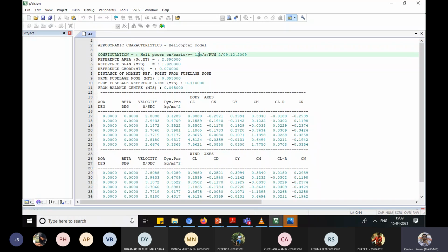But when you run the fan, then what speed you reached, correct? So if 12 meter per second is there inside the wind tunnel, then that velocity will be considered the relative velocity of the aircraft. Okay, then you should have the span, area, then reference chord. Mostly we are looking from the nose.